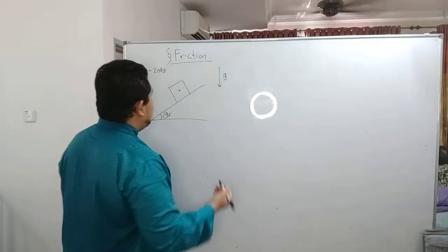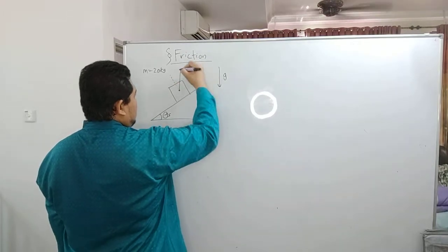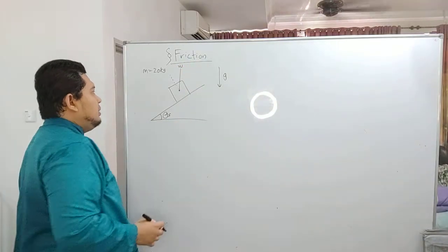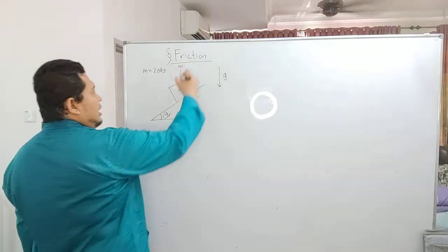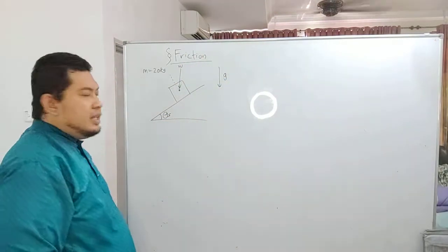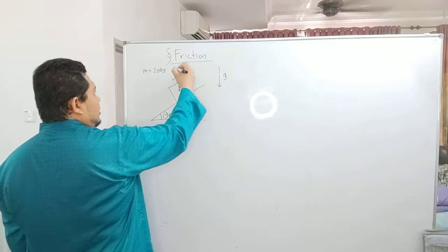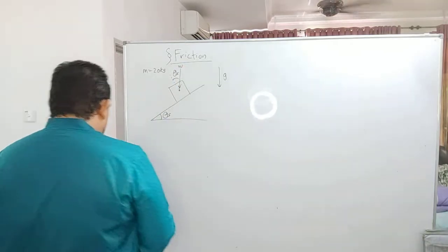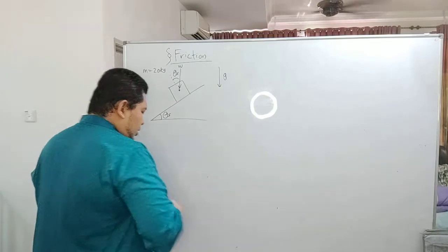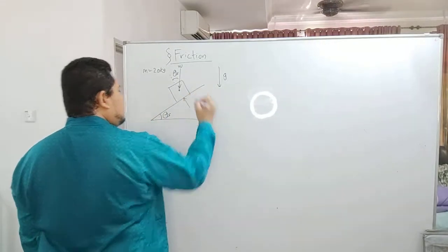acceleration of gravity. But in this case, you have to realize that the weight itself is different. It should be like this. The direction of the weight needs to be similar to the gravity direction, so the angle over here needs to be similar to this one, theta s. Over here you should have the normal force, which is perpendicular to the contact surface.